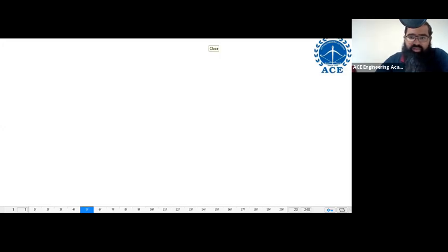If there is no flow taking place, then piezometer reading and pitot tube reading will both be the same. Point A is just some point I'm considering in a particular flow.